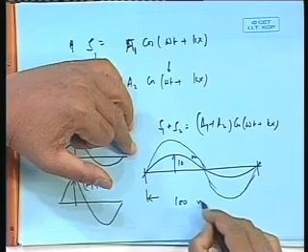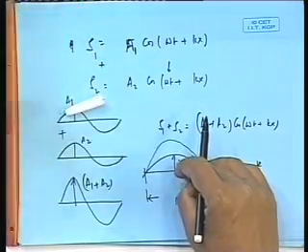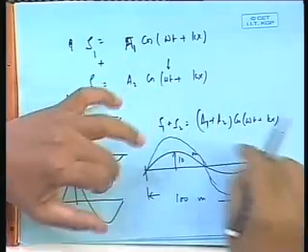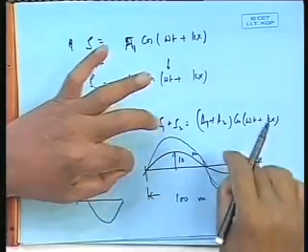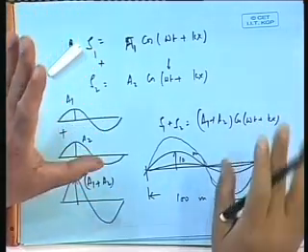Let me give an example, this is 100 meter. Now in 100 meter, a height of 10 meter is called quite steep, because by the time we will break. Now suppose I have a 100 meter long wave, 10 meter high wave. I can say that, look, it is nothing but sum of 10 number of 1 meter high waves. Now a 1 meter high wave is obviously small amplitude. It follows linear theory. So now I am adding one linear wave, small amplitude wave, plus another one, plus another one, plus another one. The resultant wave I have got is actually not so small amplitude.